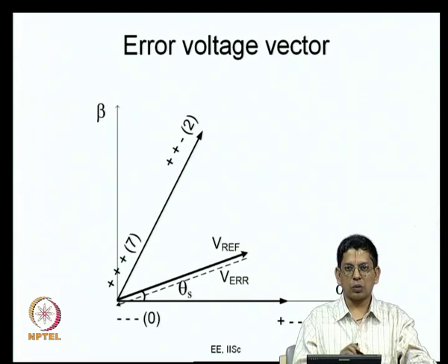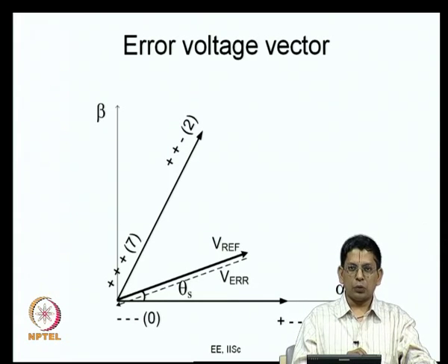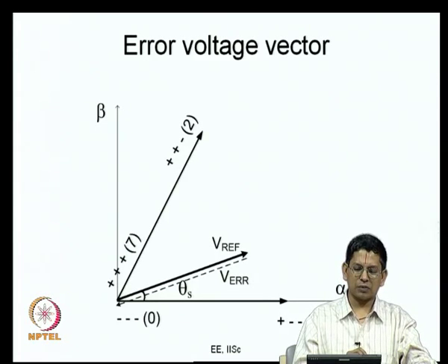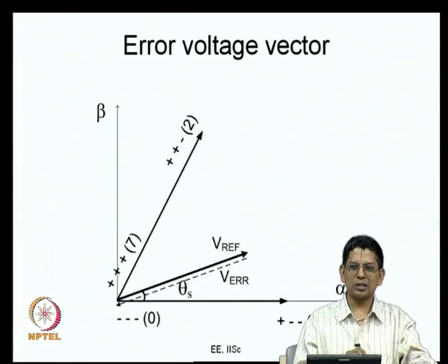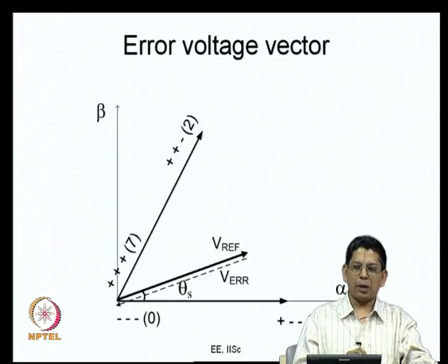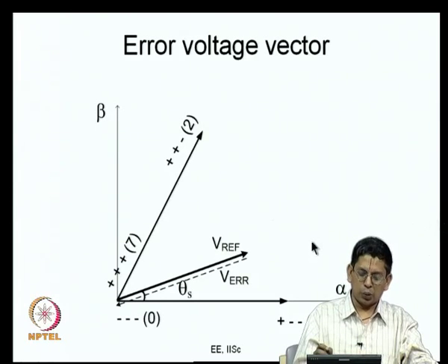So, this is to review the error voltage vector that I mentioned before. There is always a difference between what we want and what we can apply in the context of this inverter. What we want is a sinusoidal voltage, but you do not get this. So, you actually synthesize sinusoidal voltages by applying DC pulses, that is what you do in an inverter.